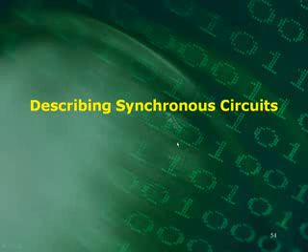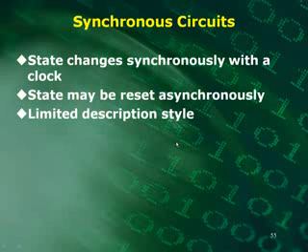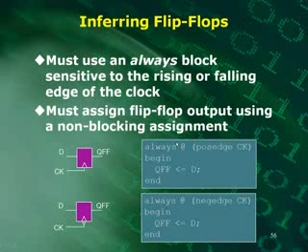Let's talk about describing synchronous circuits. A synchronous circuit is where the state changes synchronously with a clock. And the state may be reset asynchronously if you want to, but there's a limited description for this style. Okay, it's a subset of the Verilog language.